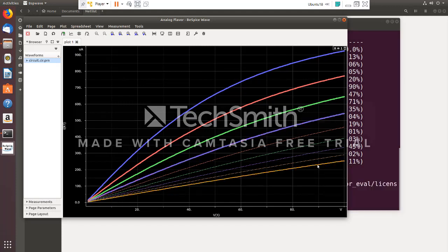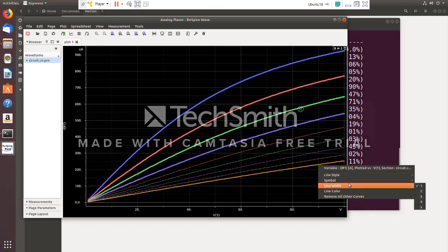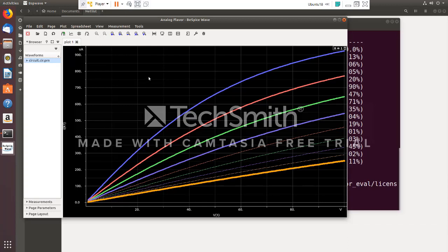So if I go to the lowest one, yeah, notice the difference. These are high currents, right? High currents mean high self-heating, right? So you see a much more prominent decrease in current. Low values of current, you don't see much because the temperature is not increasing much. So yeah, that's all.